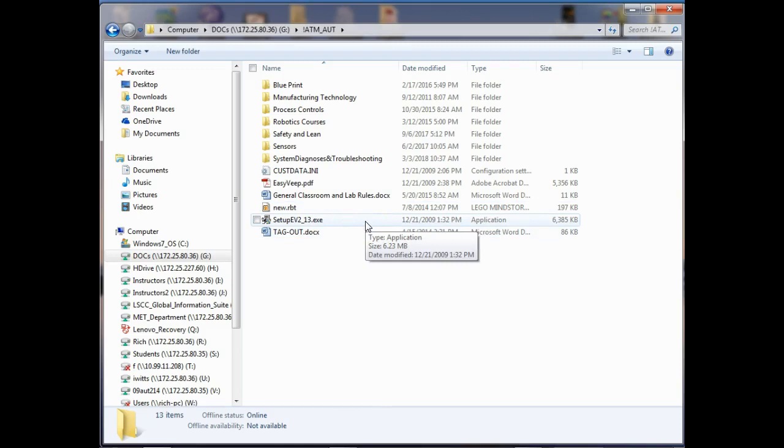People who have dealt with microprocessors call them flag registers, because they're only a single bit, either 1 or 0. They set when what they look for is true, and reset when it is false. That's why they got the name flag. It's flagging when it's true, right?